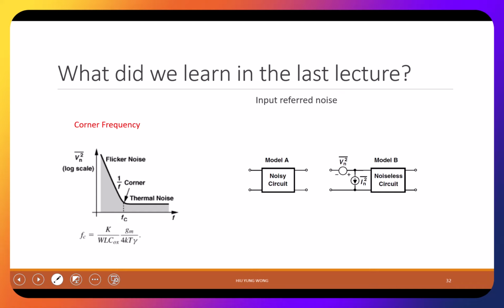Yeah, very good. Electrons get trapped and detrapped. If you remember my analogy, it's just like an army marching in front of this building. Once in a while, someone from the building pulls one of the soldiers in randomly, and maybe before I release the soldier, I pull another soldier. So the army, the current of soldiers, becomes less by two people. But suddenly, I feed them, they're happy, then I let them go. Suddenly, you may have one extra or two extra soldiers. And that is how you get the flicker noise.